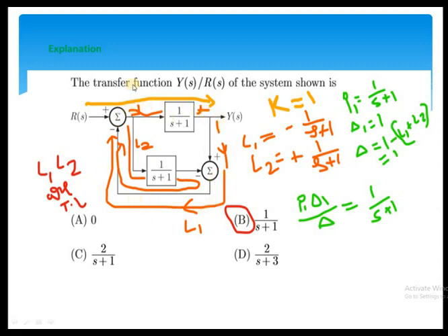What about the gain values? The path passes through the 1/(s+1) block twice, so consider this gain, and the signal comes back to the R(s) input. Here the signal feedback is negative, so you should consider minus 1 because the feedback signal is minus 1. If it is positive, you should consider plus 1. So consider this value as a gain of minus 1. The L1 loop gain is minus 1/(s+1), because multiplying 1/(s+1) by minus 1 gives the same value. L1 gain is minus 1/(s+1).